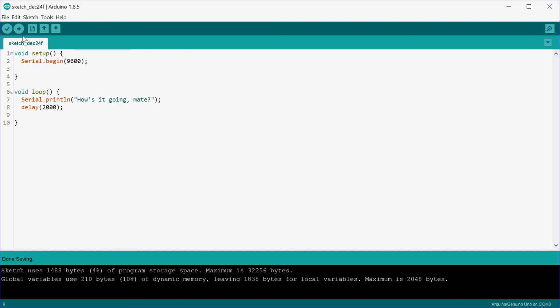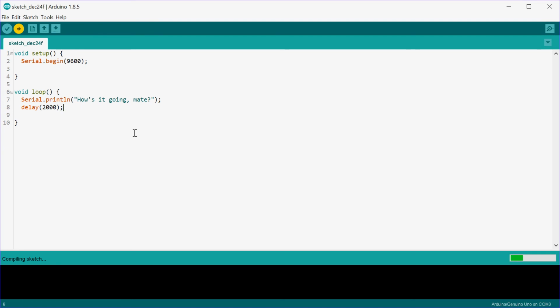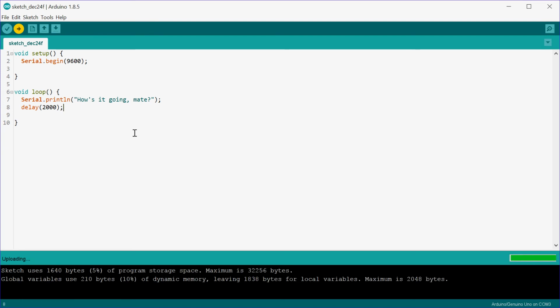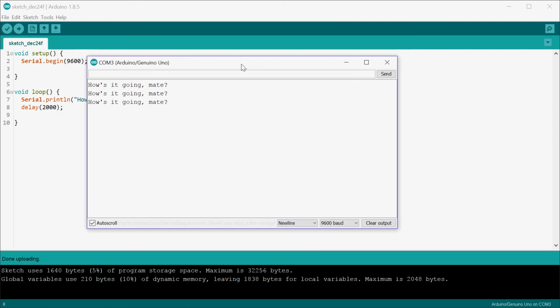Let's now upload this. Press on that one. It'll compile once again. And it's done. Let's now go inside the serial monitor once again. We can see it says, "How's it going, mate?" Then it pauses for 2 seconds. Once again, 2 seconds, boom, boom, boom. So it pauses for 2 seconds each time it sends, "How's it going, mate?"